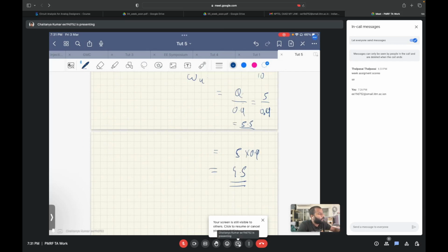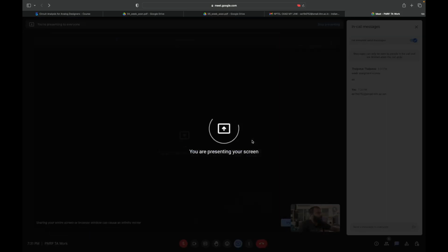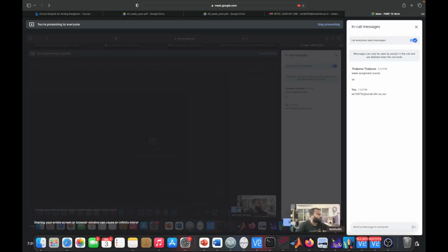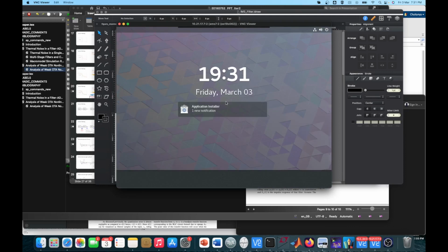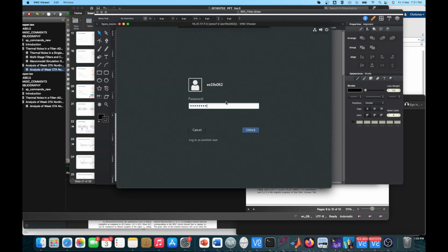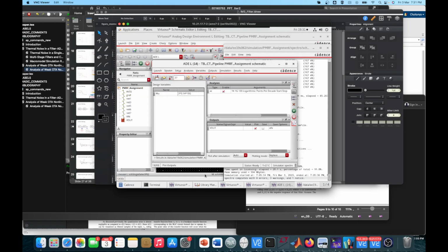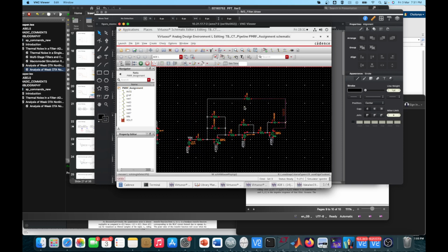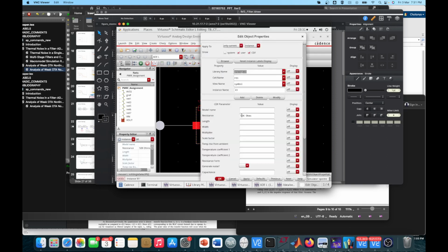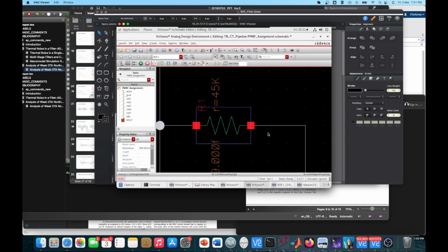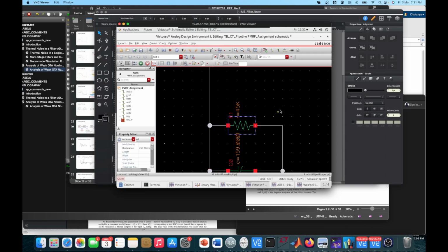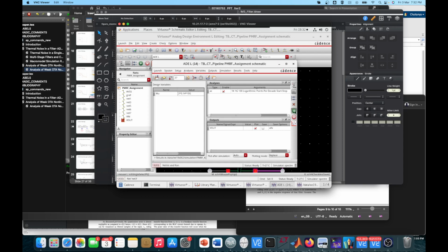So let's try that also in the simulator. Here, instead of 50, we make it 45. Had the op-amps been ideal, your quality factor would have been 4.5, but now it will be 5 because of the calculations we did.